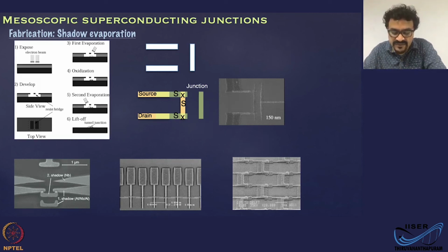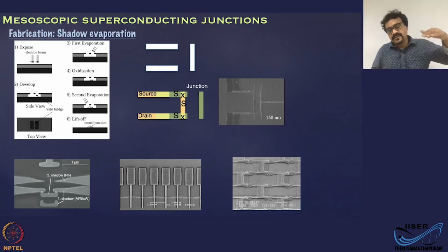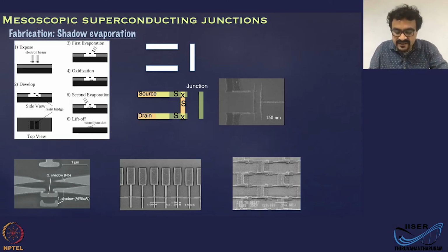Now what you would do is you will metallize by a process called thermal evaporation or electron beam evaporation. It's called physical vapor deposition. Okay, from one angle. Once you do that, you will get something like the yellow region here. So you will get a region which looks something like this. Okay, this yellow here, and this yellow region here, only that.